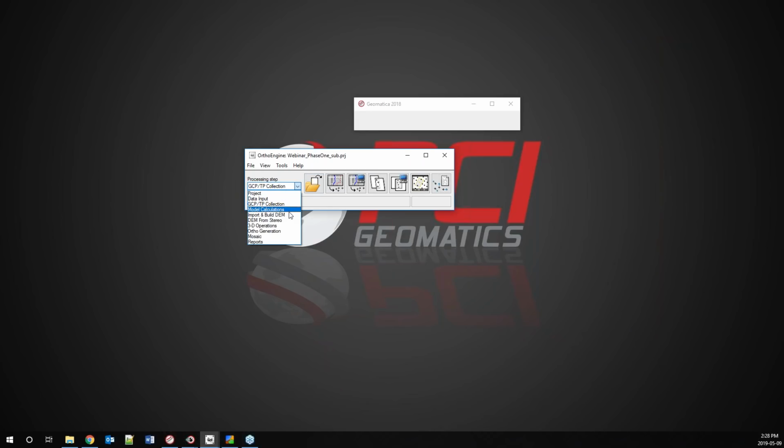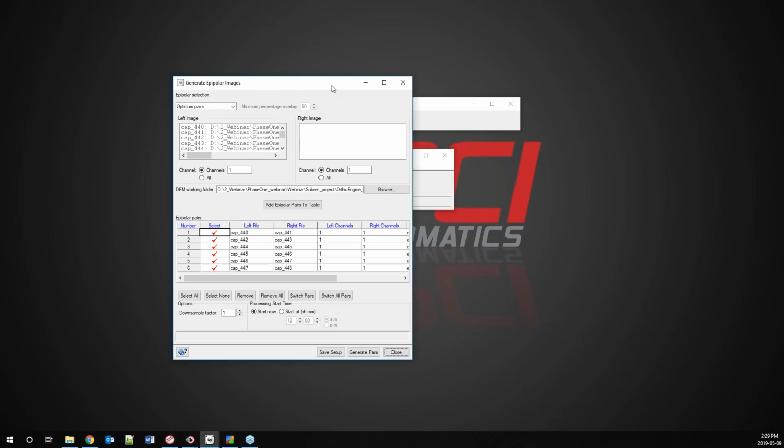The next operation is our DEM from stereo. As the imagery was captured with stereo overlap, we can leverage our two-step DEM extraction process to extract the DEM. The first operation is creating epipolar images. The epipolar generation tool aligns the stereo pairs by removing the Y shift so features are lined up in the x-axis. This will enable the system to run the elevation triangulation in the DEM extraction, which will generate, filter, smooth, and geocode the epi-DEMs, then merge them all together to form one single DEM.